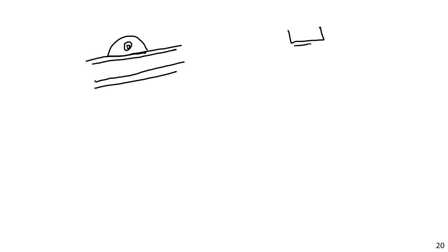So a pad eye is something like this. You can maybe have this attached to a beam here, maybe a wide flange, something like that. And this would be welded on. And then there would be a bolt going through here. If you looked at it from the side, maybe I can include the beam as well, it would look something like this. And then a bolt would be passed through here, and then this could be lifted up with a crane. A crane would be a good example. Any kind of lifting mechanism.